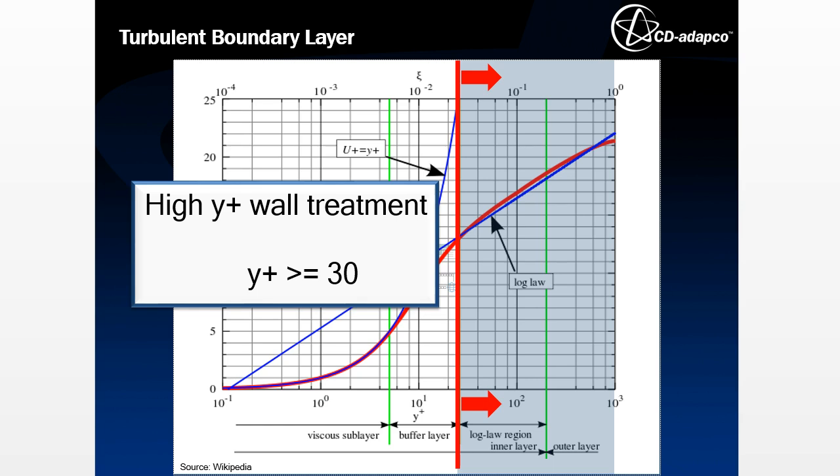While there have been successful applications in the marine and civil engineering sector with Y plus values as high as 500, a value of 100 is recommended as best practice for most applications and should not be exceeded without proper validation.